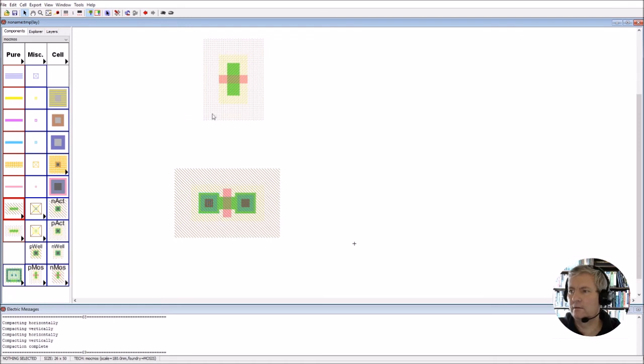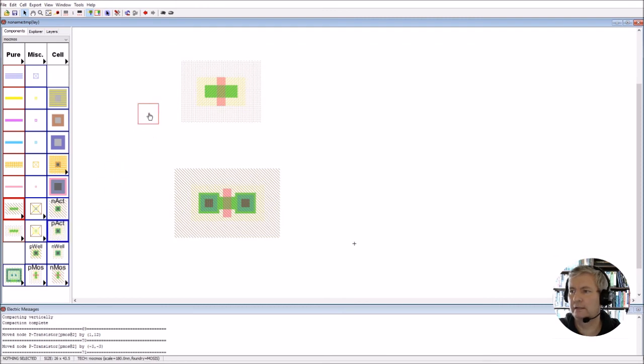So if we do the same up here, we could click on this, we could do Control J. Now in this instance here, we're going to have a PMOS device, so we have to get access to this P active region. So I'm going to have to use this via here. So that's a P active, and we can click on that there, and we can get another one of those and click on and put it that side.